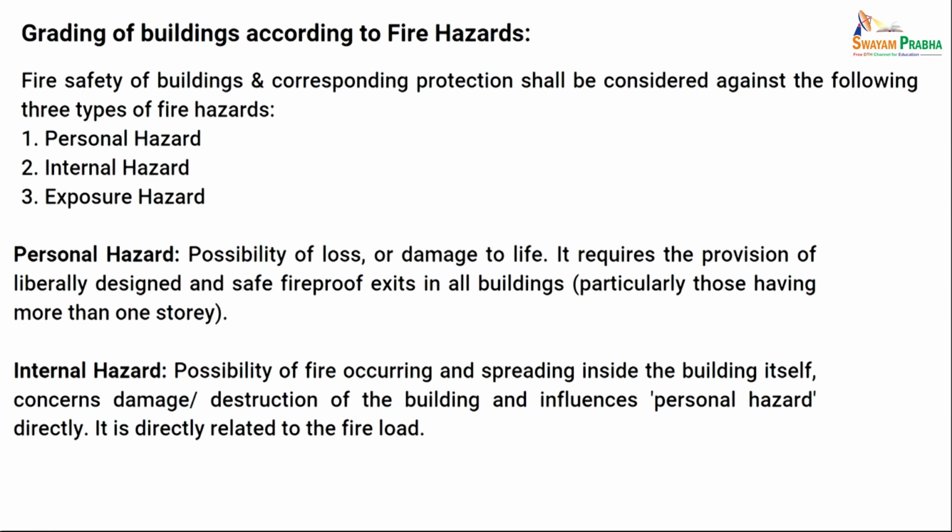Coming to grading of buildings according to fire hazard, fire safety of buildings and corresponding protection shall be considered. We consider personal hazard, we consider internal hazard, we consider exposure hazard when we talk of conduction, convection and radiation. Personal hazard is the possibility of loss or damage of life. It requires provision of liberally designed and safe fireproof exits in all buildings, particularly those having more than one story. At ground level, people can escape very easily.